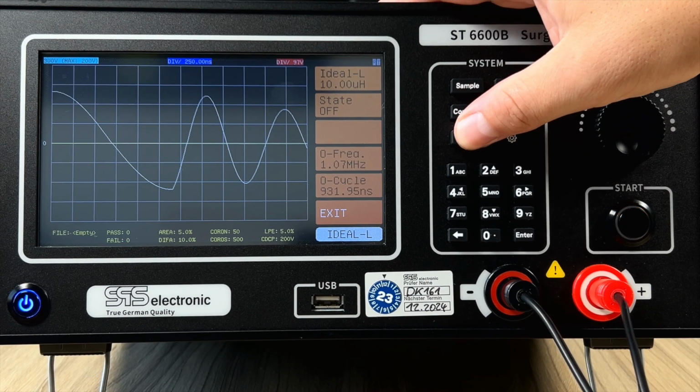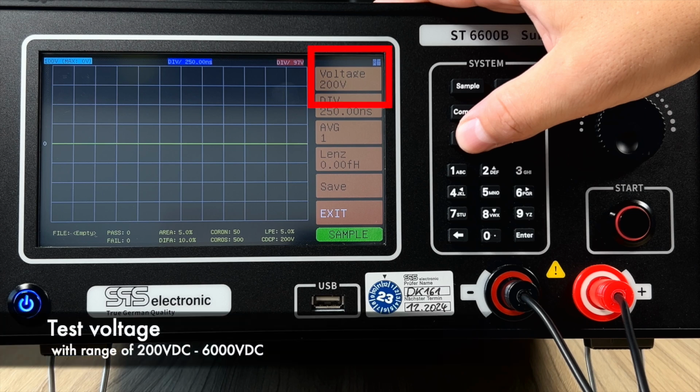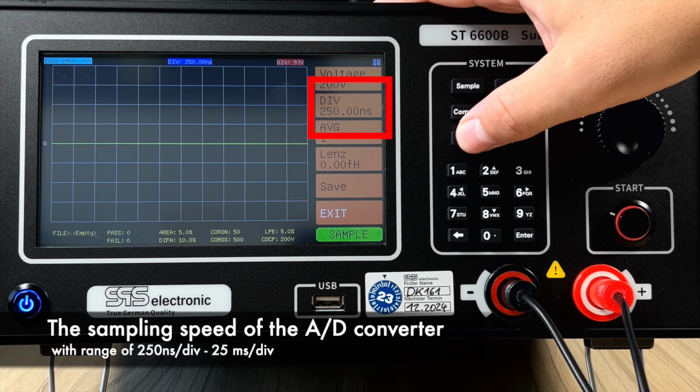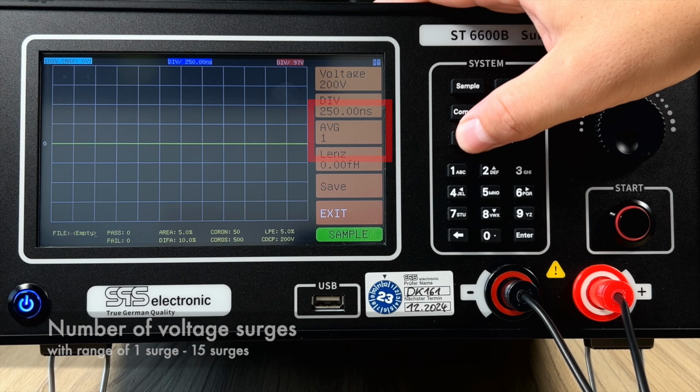The next step is sample, where we will set up our master curve. As a first setting, we have voltage, where we will set up our test voltage between 200 volts and 6000 volt DC. The next one is DIV, where we will set up the sampling speed of the AD converter. In a step AVG, we will set up the number of the voltage surges.